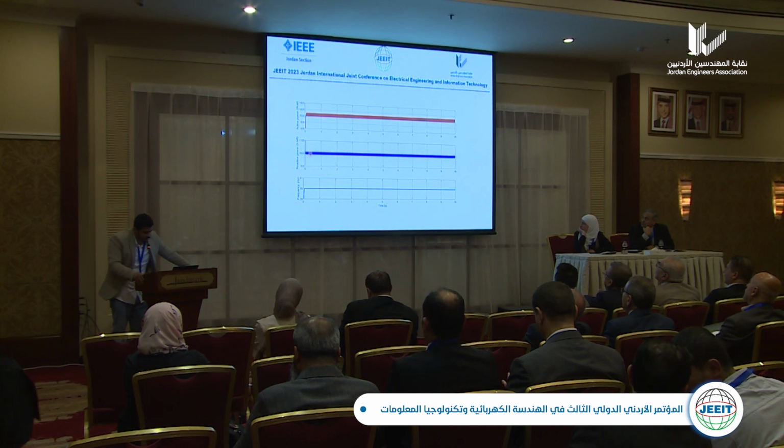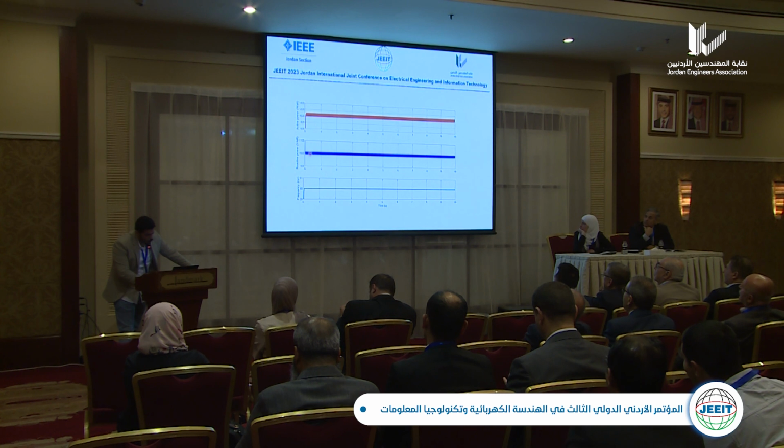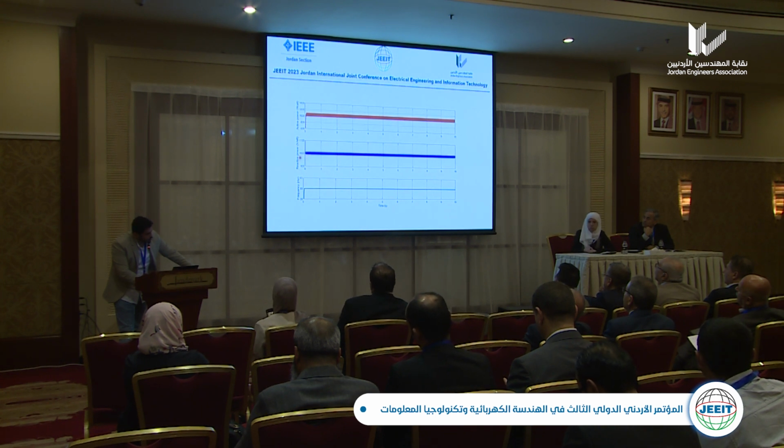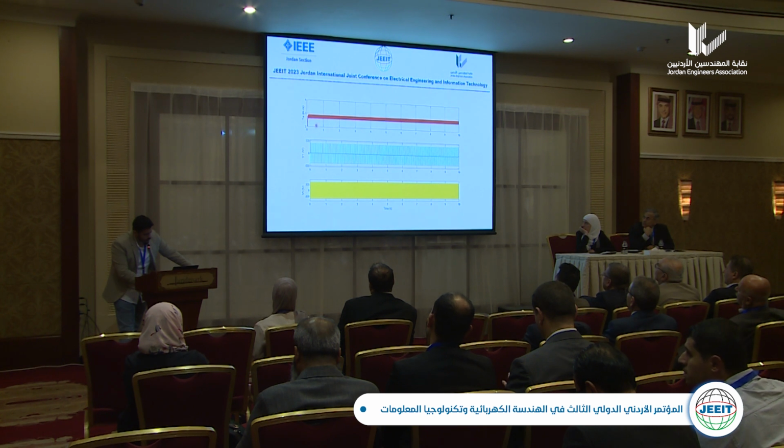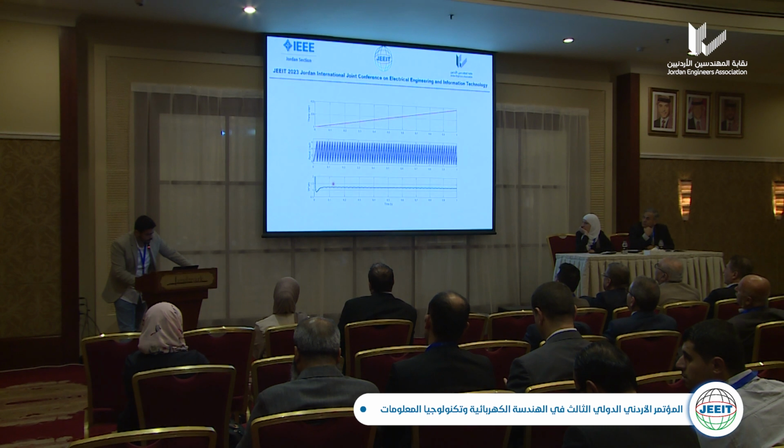This is the result for the synchronous generator for the single machine infinite bus system. We want 1000 watt for the active power, and we get 1000. For the reactive power, we want 1000, and we get 1000. For the frequency, we have 60 hertz. Here is the torque, between 2 and 3, which is good, and here is the unfiltered voltage signal and the filtered voltage signal. Here is the reset operation.